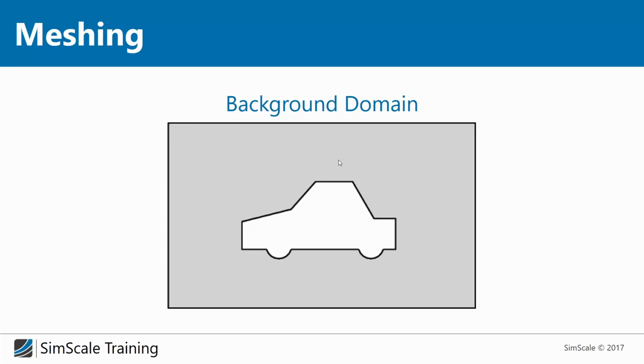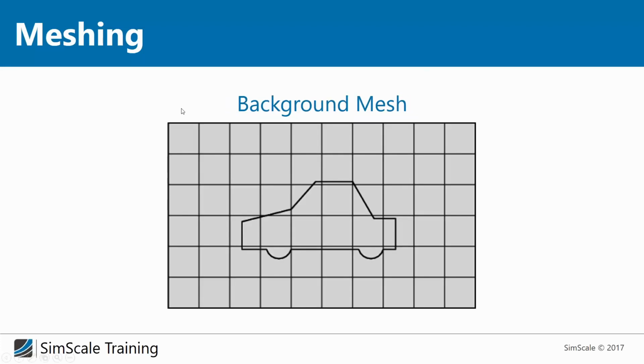And when doing CFD, first of all, we need to create the mesh, which means we need to tell the computer where we need which kind of accuracy. Basically, what we're doing is dividing our fluid domain into a finite number of simple shapes, in this case hexahedra. Instead of calculating the simulation result for every point of the domain, which would lead to an infinite number of control points, we just calculate the solution, pressure, velocity, and all the other flow quantities only for the center of the cells.